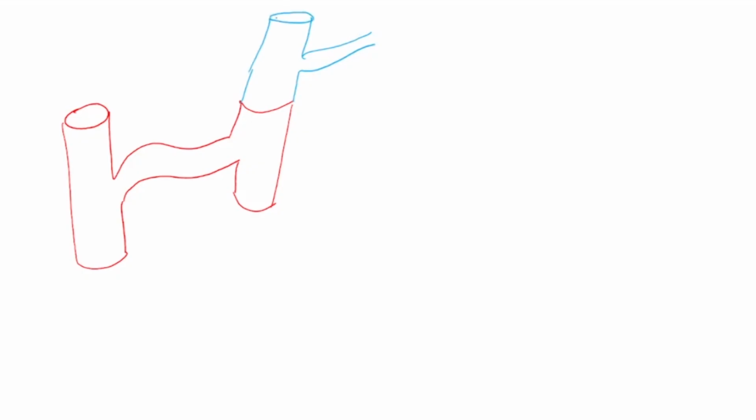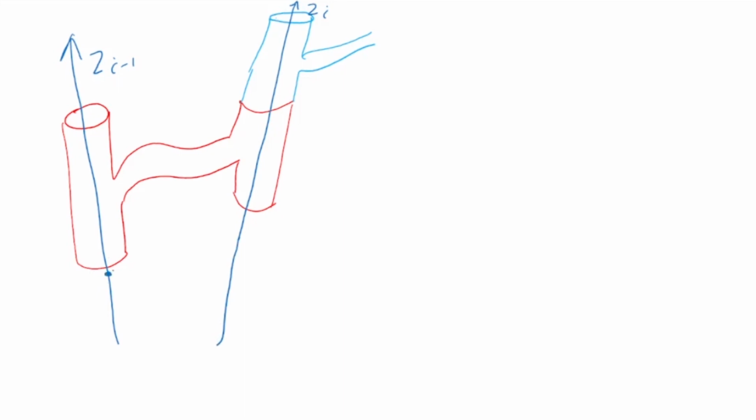Now, we assign our z-axis first. The z-axis is the axis of rotation or translation. So this is my z-axis, which I can call z i minus 1. And this is my next z, which is my z i axis. Next, we assign our x-axis, which is along the shortest distance between the two z-axes. If I draw this as the shortest distance, then I say my x i minus 1 is here. And the next one, x i, is on that frame.